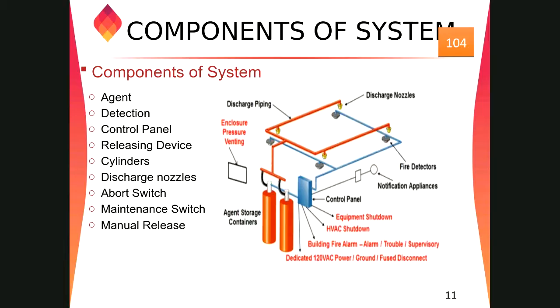No, that will only open if the pressure inside the room goes more than the design limit. If it goes more than that, it will open for some pressure limit only, and it will close within a second, just to relieve the pressure. It will not open instantly.